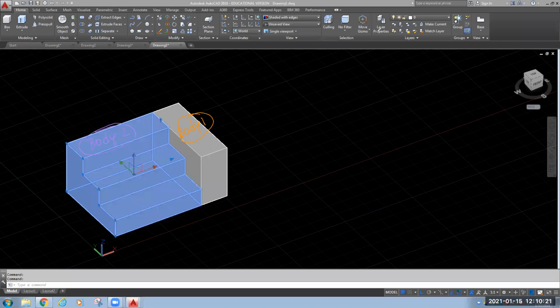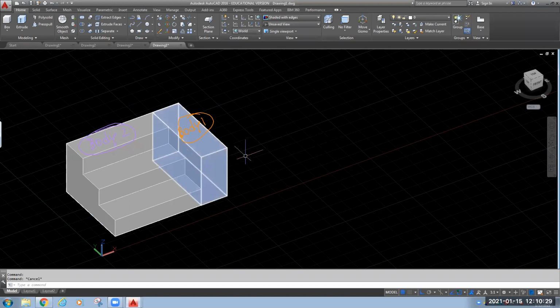So here I am going to tell you one new thing, that is your Boolean operation. What is Boolean operation? Okay, so the point is I want to join these two different bodies to make it a component. Okay, so I want to add two different volumes. What are those volume? Body number 1 and body number 2.